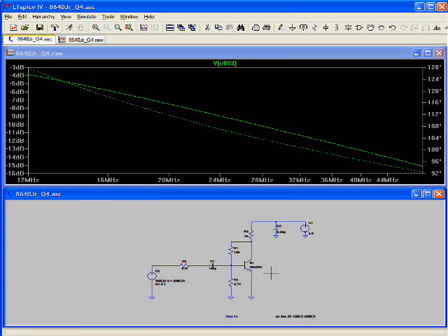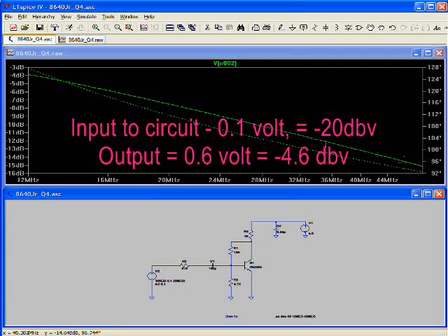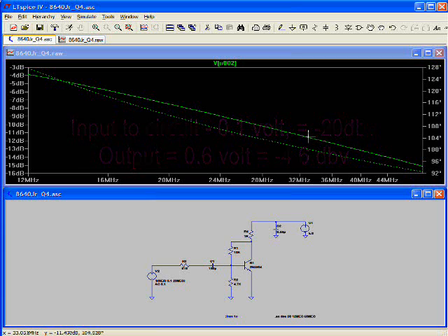So this is a real transistor. You know, it's kind of not unusual to see gain fall off at a higher frequency. So in the frequency range that this is designed to be used, which is about here, it runs so maybe 5 dB down from the input to 15 dB there, but we only go up to 31 megahertz, so about 11 dB.